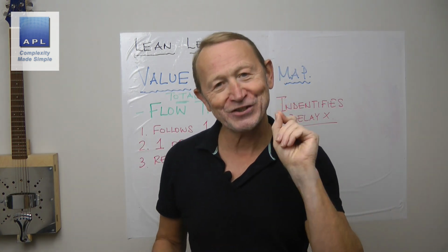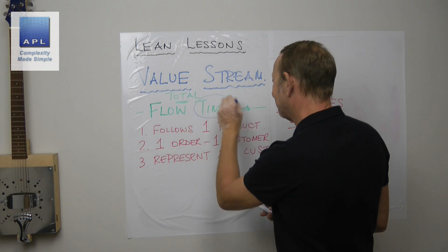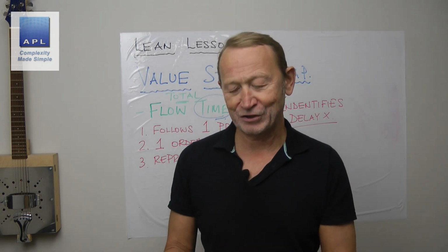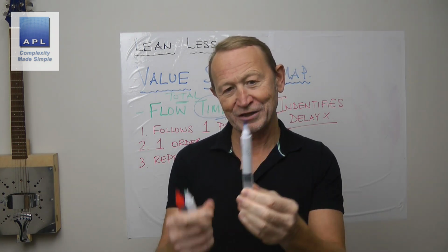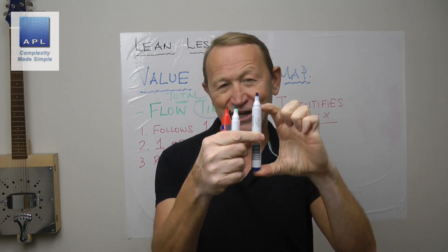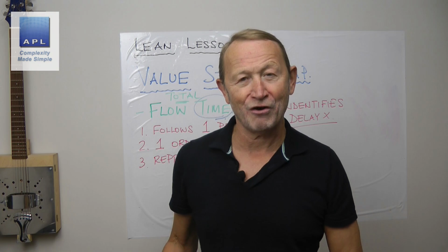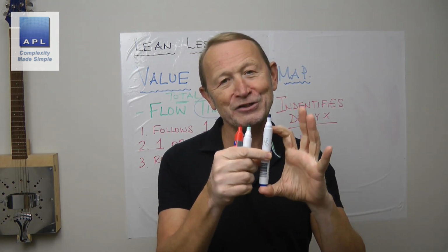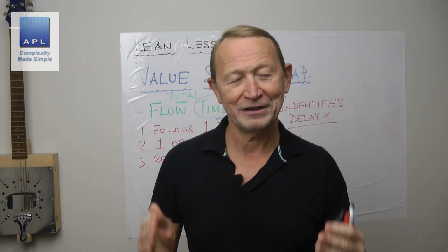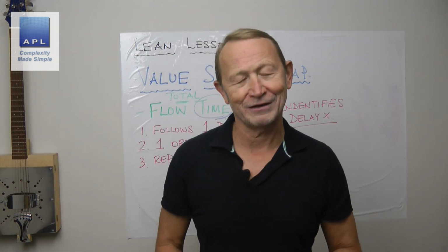In lean, waste is very particular, and most importantly, waste is measured in minutes. How many minutes did you physically add value to this? So obviously when you mold this piece, it might take 30 seconds to mold the piece. But then the item sits for 2 weeks in stock. 30 seconds is the value, 2 weeks is waste. And it's measured in time. And that's the standard way, standard work to measure standard waste.